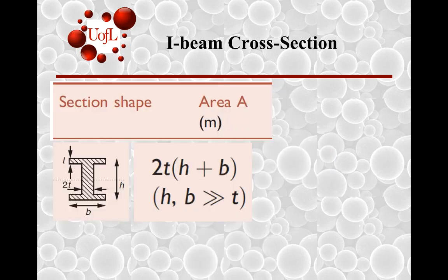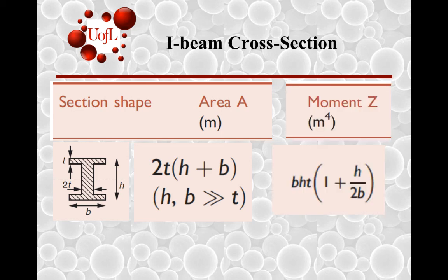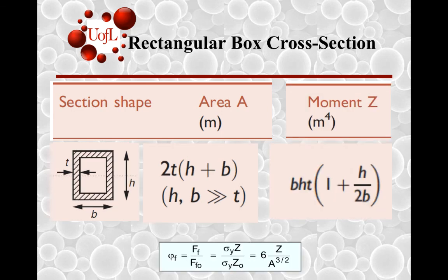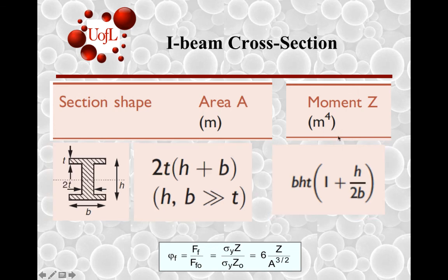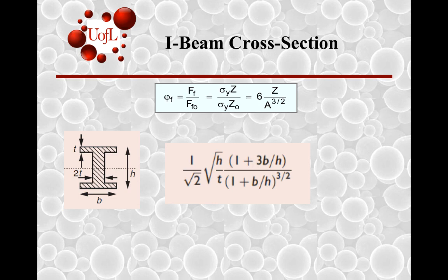You would imagine then, based on how we saw for the stiffness limited design earlier, that for the strength limited design, again, the terms would be the same for Z, A, and the shape efficiency factor. So we've taken some common cross sections so far, and for a stiffness limited design and strength limited design, derived shape efficiency factors. We had earlier seen how that can be used in an E versus rho plot for a stiffness limited design. So we have also come across